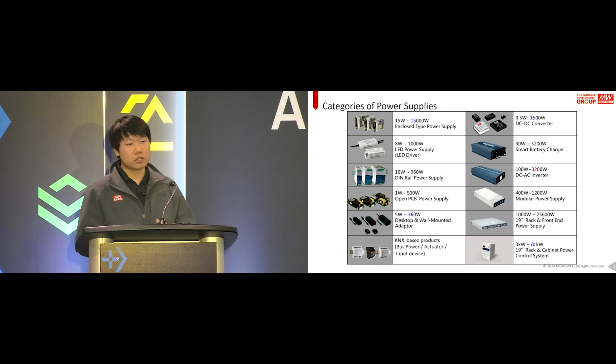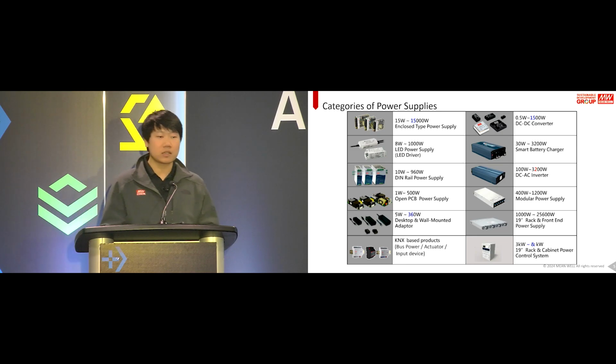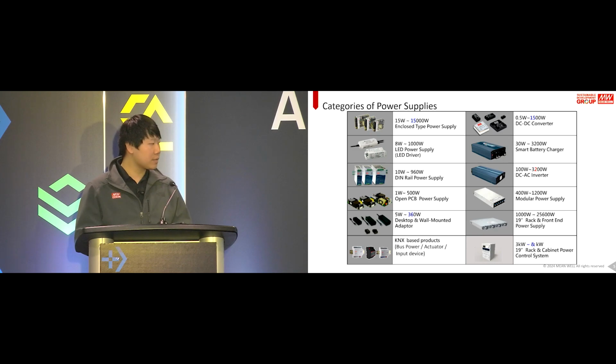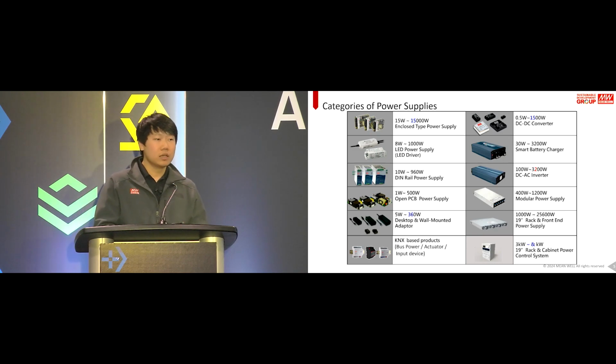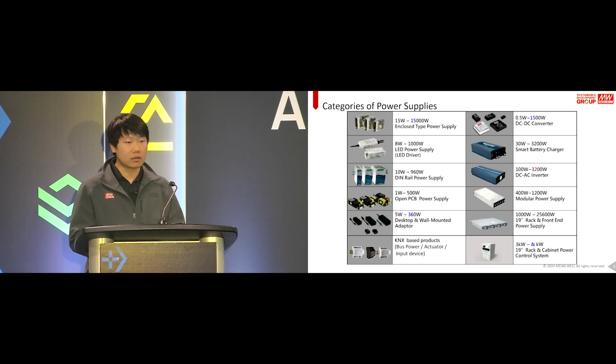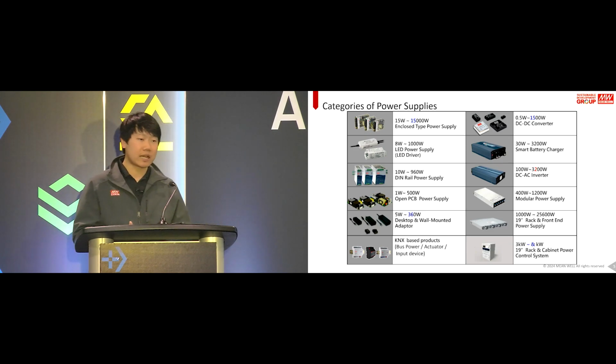For the enclosed power supplies, typically the higher power units are packaged with fans or other cooling mechanisms. But for lower power products, the open frame will suffice. And if the customer's application has fans built inside, it can already provide sufficient cooling without the increased space and size of the enclosure.